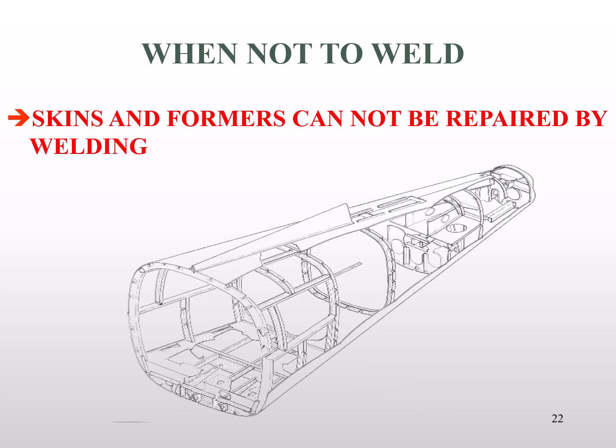The most commonly used alloy of aluminum in structures for aircraft is 2024 T3. The T indicates that it has gone through some form of heat treatment. The 3 indicates what kind. So because it has gone through a heat treatment, a weld will destroy that aluminum's strength and rigidity properties. Therefore, it is not acceptable to weld on any structural aluminum part.